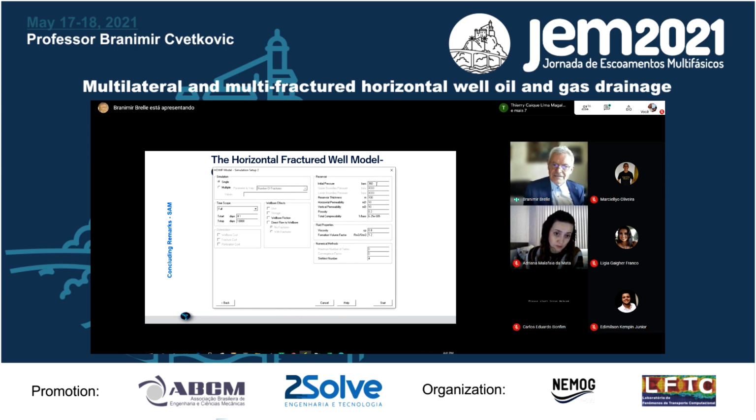And then I have bars. Let me put that I have 400 bars. Then I have reservoir thickness is, let's say 300. Then I have horizontal permeability and vertical permeability at 10 millidarcy. Okay, porosity is 20%, sorry. And total compressibility is normal as it is. Viscosity is 0.8, it's oil. And formation volume factor is 1.2. That is okay. Stehfest number is this.